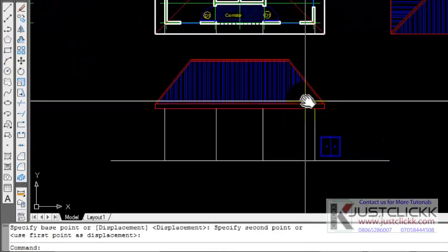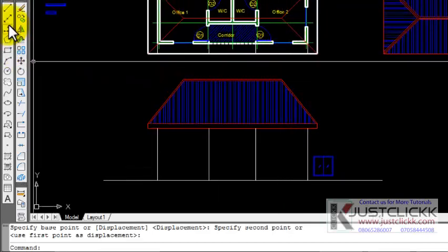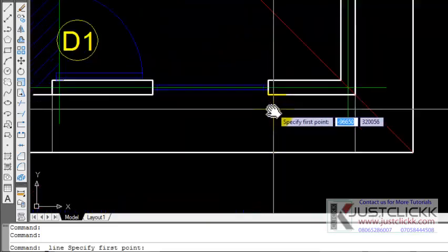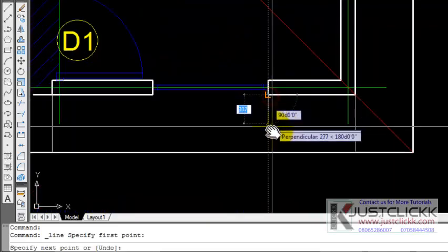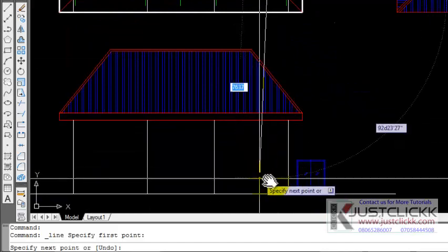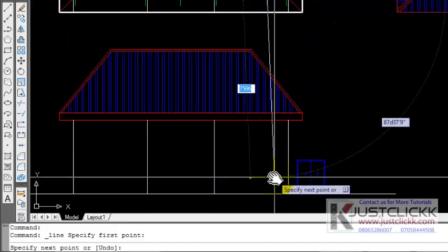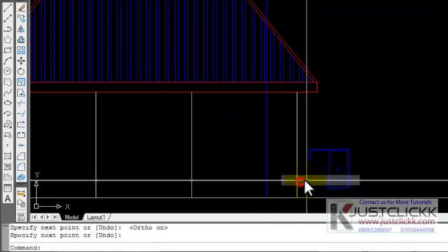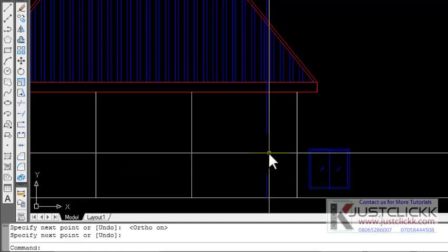Let's look at the plan. Alright, window is here. So we will track down, pick a line tool. So from your floor plan, to be very precise, click at the end of the window, and then enable your auto now, because you need to bring it down. Enable your auto, you're bringing that line down to this point. So this is where the window begins.